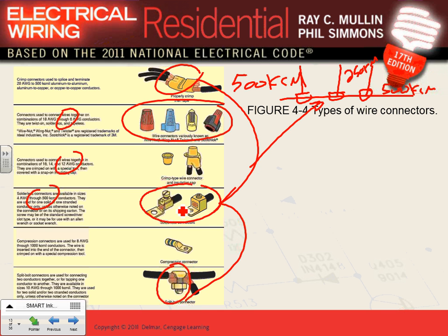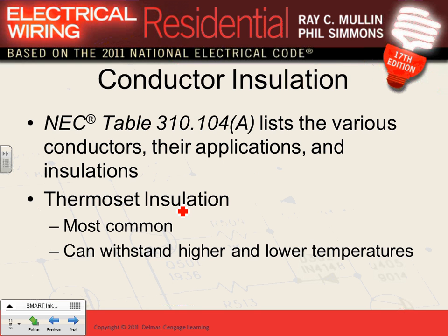Compression connectors, these are great for a lot of application. If you can see 1000 kcmil, so you crimp that one on one end of the cable, and from the other end you land it on the lug of that feeder, and you torque them. Any comments, guys? Any questions about these connectors and wire nuts? These really, for the most part, being designers is FYI.